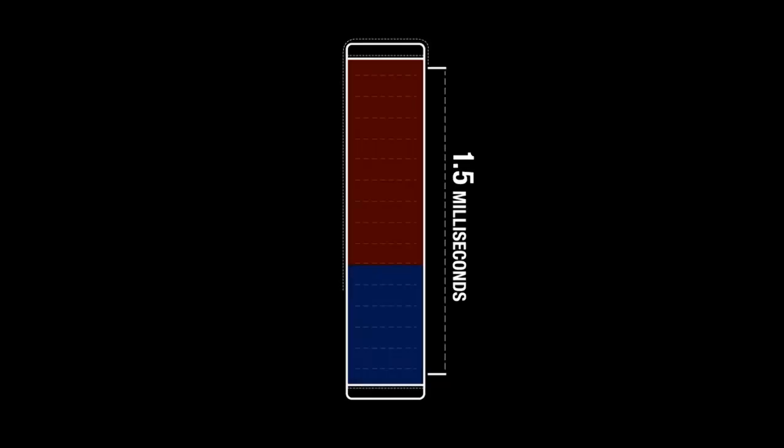When we apply fueling compensations for different air or coolant temperatures, for example, we don't want to apply that compensation on the dead time values, only on the actual injection event. Likewise, injector dead time is important to compensate for when we're determining the mass of fuel going through the injector.